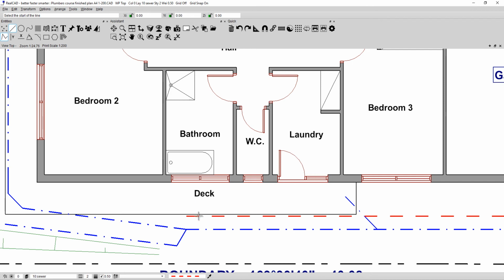I'm going to start my line here, but again I don't want it to be at right angles, so I'm going to hold down the Control key. Okay, and you'll see that that gives me a start position without being at right angles. Wasn't selecting this red line. Press down the Shift, gives me a 45, that takes me to there. I'm going to come up to here, across to, well, in fact I might just come across to, that's a good point.